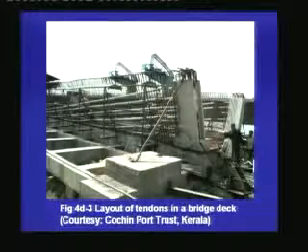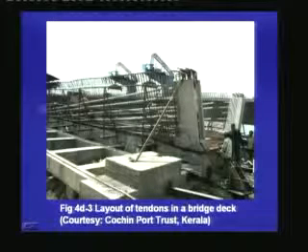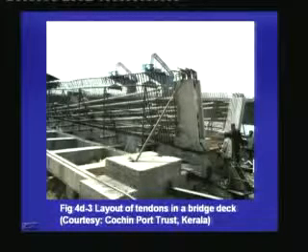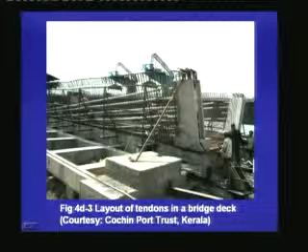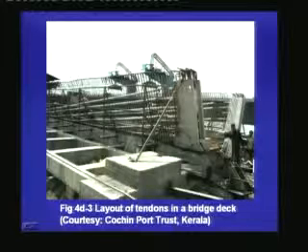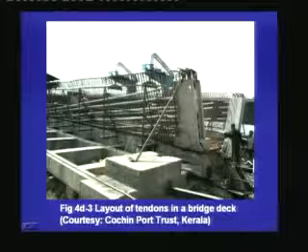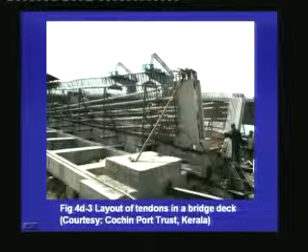In this photograph, we see that the tendons are more concentrated towards the midspan, but as we are moving towards the support, the tendons have been spread out. This is helpful. First, it helps us to anchor the tendons. The anchor blocks are spread out at the end, and also the stress concentration has been reduced because the anchor points are spread out.